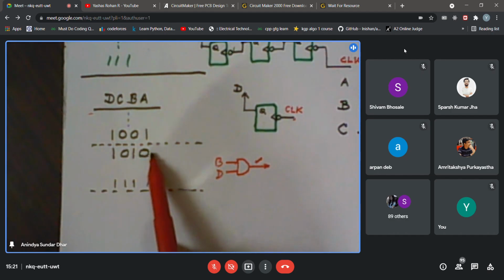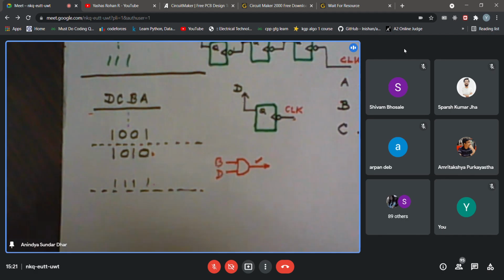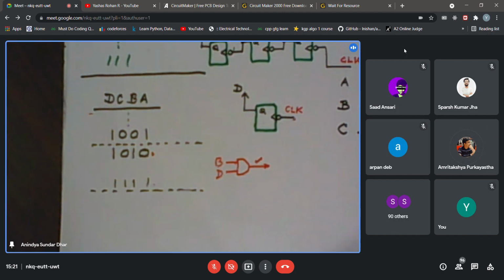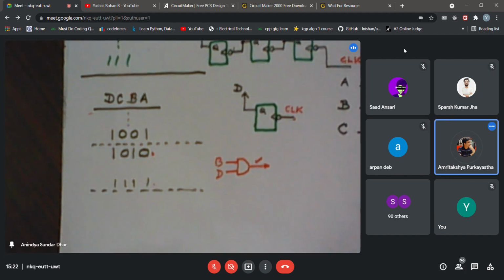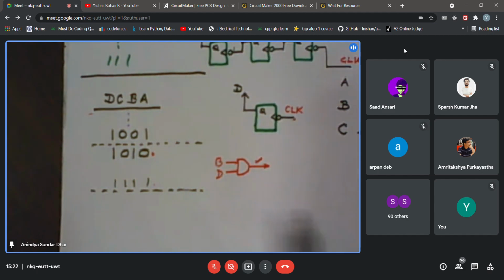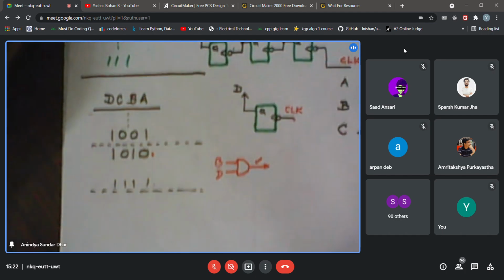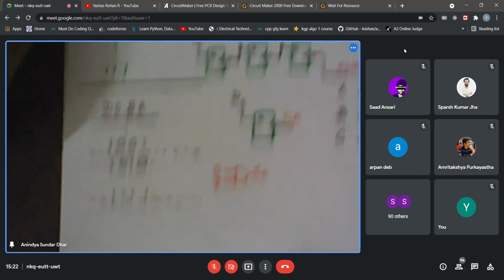But in that case, state 10 will also come, and my intention is to get 0 to 9 only. Yes, for a small time instant that would come. It will be a very short-lived state. Its lifetime is equal to the AND gate delay plus the reset delay, which will be much smaller compared to your typical clock period.